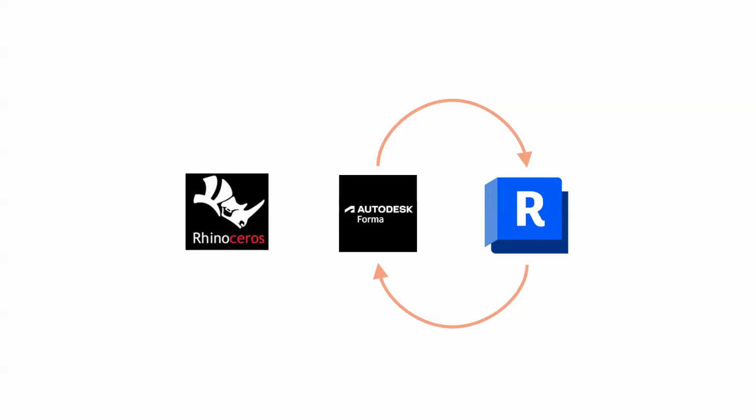If you don't want to draw in Forma, you can absolutely draw in Rhino. So this is a bidirectional sync in that you can take the Forma context and bake it into Rhino, start designing in Rhino, and then push your building back into Forma to run the analysis. And both of these are fileless syncs. So you're able to use the plugin and repeatedly push your proposal or push your model from Rhino into your Forma proposal and iterate as you go.